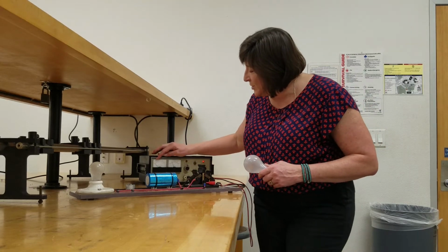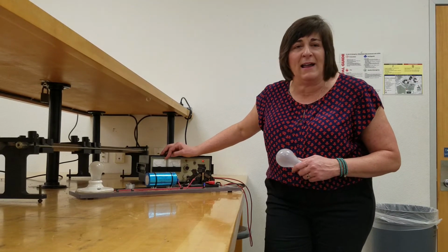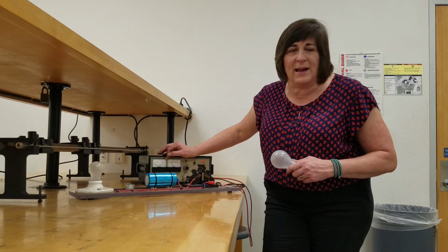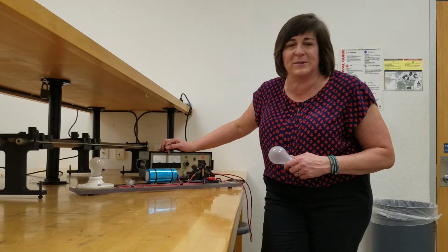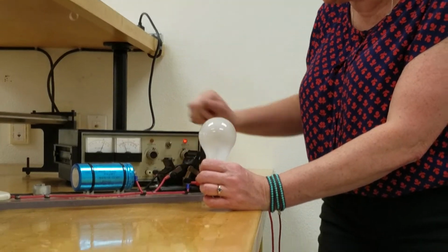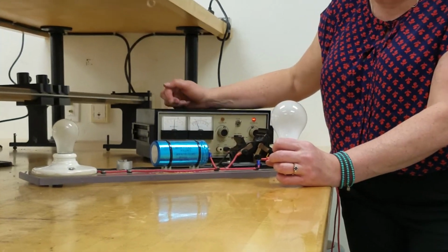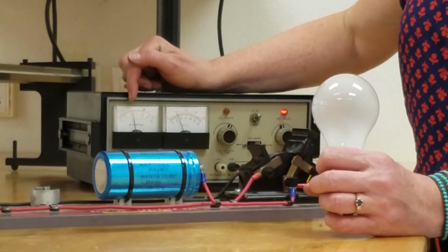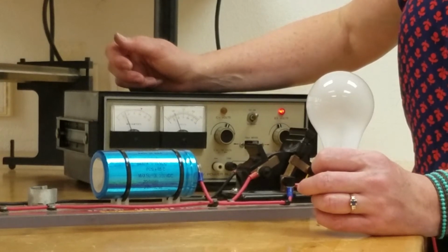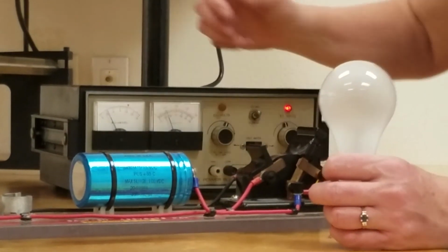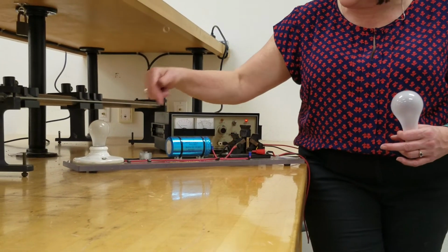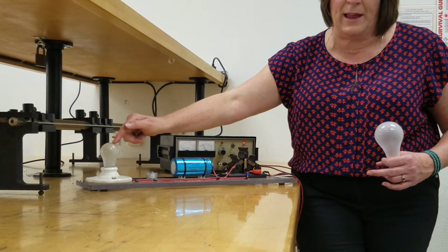We'll learn about why that is next week. But if you watch this meter, you'll see the current go high and then slowly go back down. So I'm gonna watch it until it goes down by about 95% of the way so that the capacitor is fully charged. Okay. So let's charge up. And as you can see, the meter is showing us that the current's going down, down, down, down, down. And so we probably got about 95% of the charge on there now. So what we're going to do is when I flip the switch now, I'm going to connect the capacitor just to the light bulb itself.